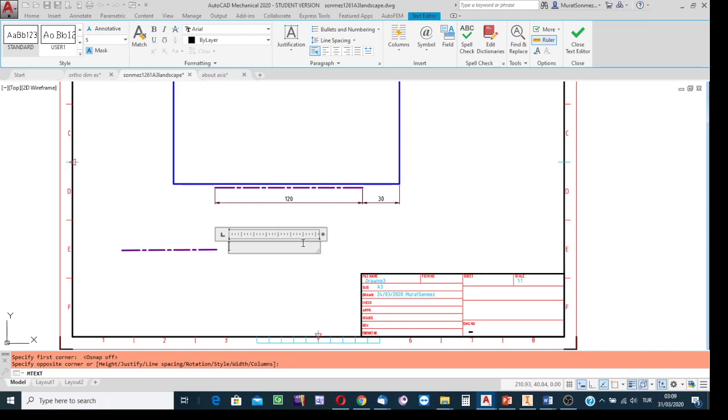And then the rest, write the text. In this example, it is to say that the surface is to be hardened. The portion of the surface which has been indicated by the chain line is to be further hardened. Surface hardened. In writing technical notes, we use the past participle. Surface hardened.